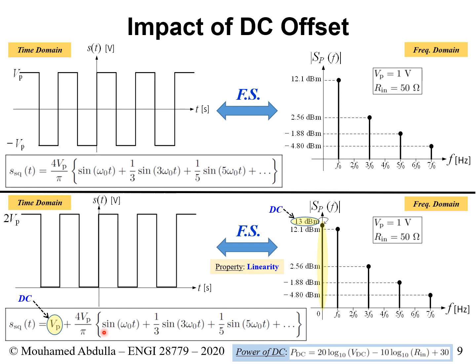The other approach that you could do is you could use the linearity principle of Fourier series. Essentially, what you say to yourself is, I have this signal. I add another signal that is only flat, across all times with a certain voltage value. And then when I move it to the frequency domain, the linearity will stay the same. So I look at the Fourier series of the flat one, which is only a spike at frequency 0, and I add it to the other spikes that I got for this one.